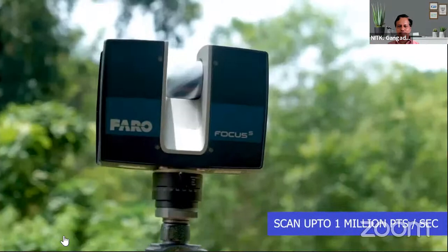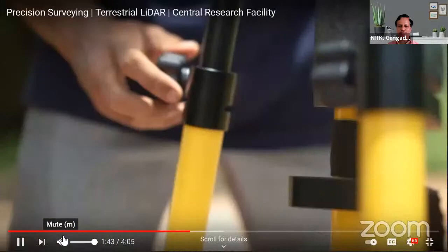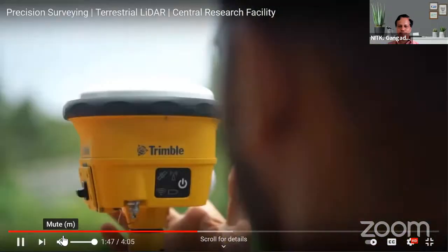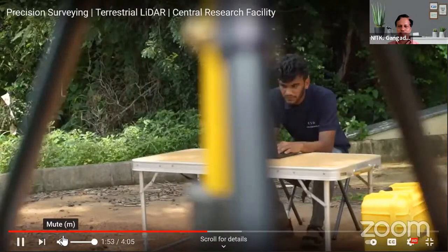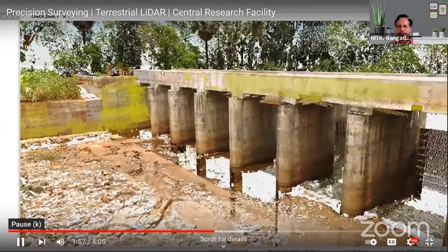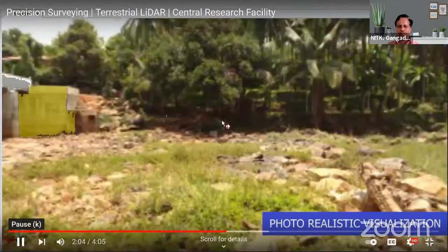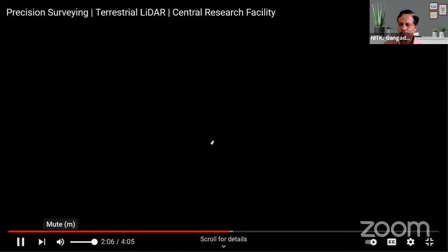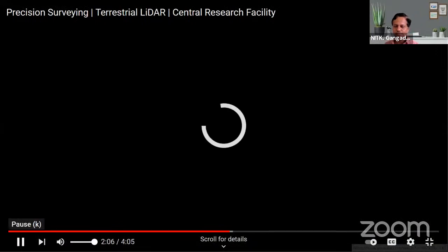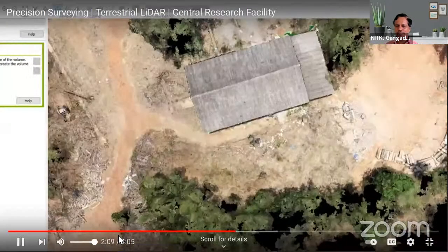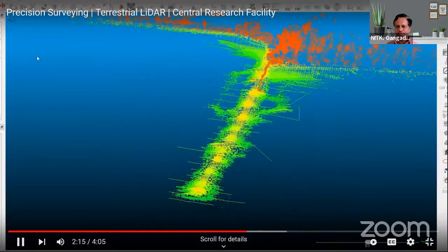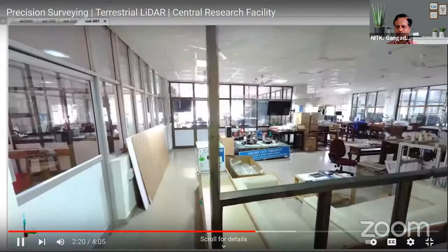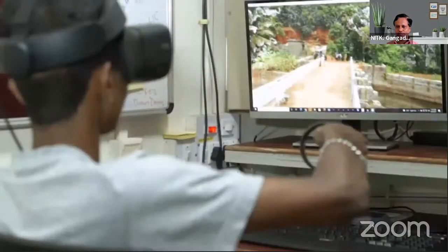For georeferencing of the whole project, differential GPS is employed. With the help of GPS satellite connections, the exact ground coordinates and elevation of the area is collected with centimeter level accuracy. Post-processing of the collected data is done with the FARO Scene software. The scans are stitched together so as to get a photorealistic, virtual, 3D model in RGB format. From this data, we can carry out analysis such as area calculation, cutting and filling, volume estimation, comparison of field measurements to its design drawings, 3D printed models, building information modeling, BIM, creating virtual reality, etc.